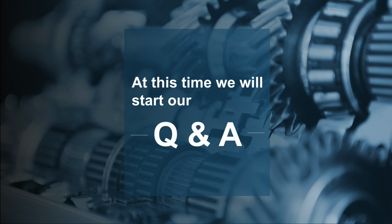Okay, Bill, and thanks again for that answer. This next attendee looks like they have a two-part question. How does the AGMA quality level affect strength, and does it affect accuracy? AGMA quality level, it does affect strength and accuracy by tightening up the tooth profile tolerances. And then it also, because of those tighter tolerances, reduces the amount of what we'll call, quote unquote, imperfections that are on that tooth surface.